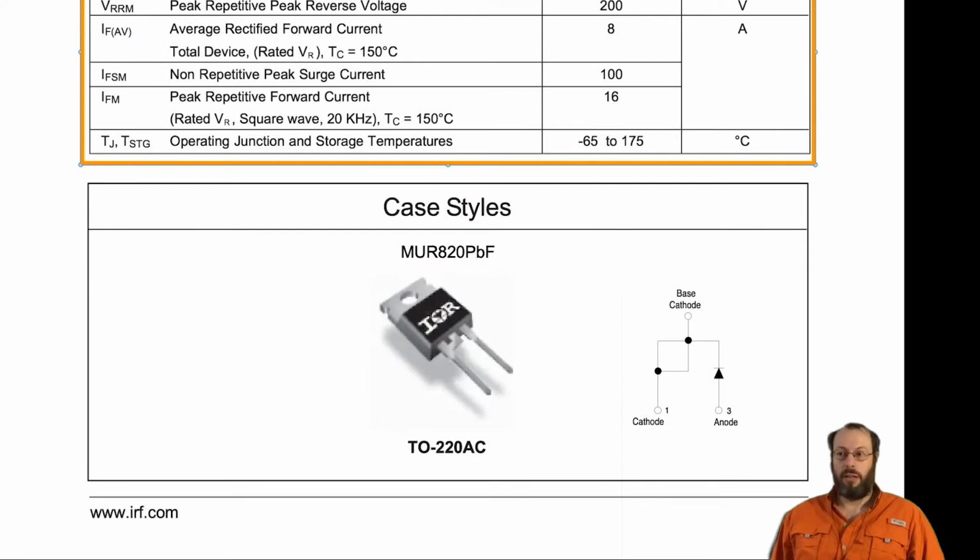Physically, this diode is shipping in a so-called TO220 package, which is a very common package in power electronics. It has 3 leads because it is also used for MOSFETs, where in the case of diodes, you actually short 2 of them out because you only need 2 connections.